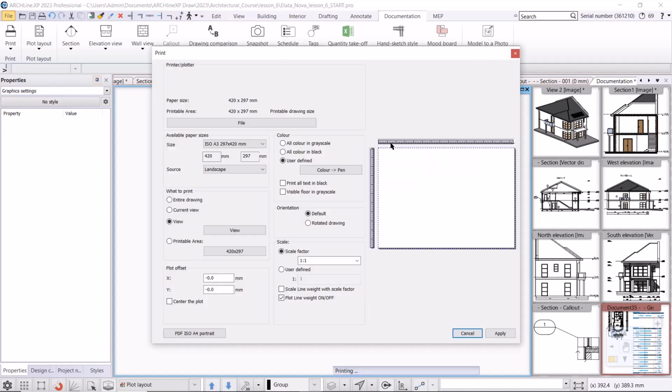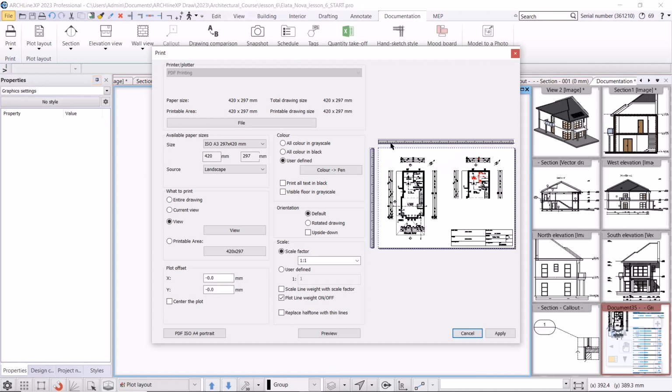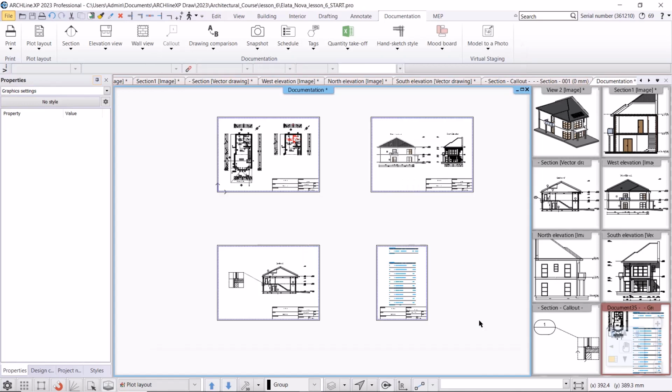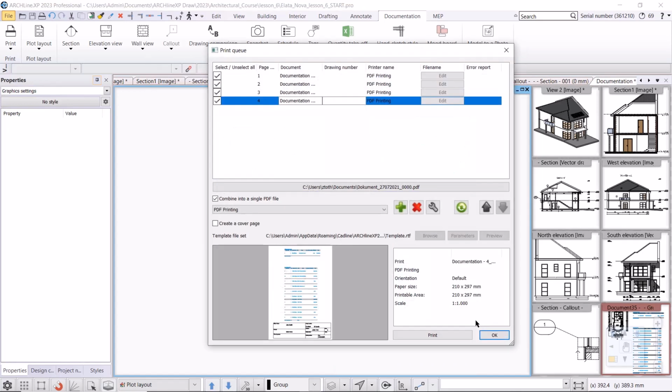We need to configure its parameters. Usually, we don't need to adjust much here, we mostly check. We want to print A3 landscape format sheets. The scale is 1:1, as we're printing A3 sized sheets in a 1:1 ratio. I won't modify the other settings. Use the Apply button to apply these settings to the plan sheets.